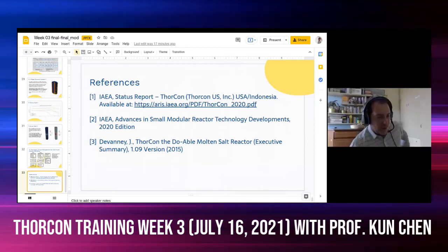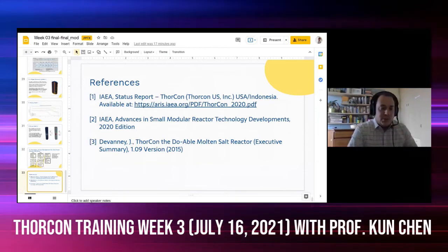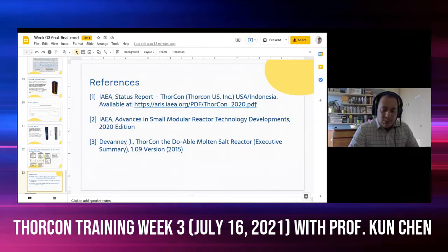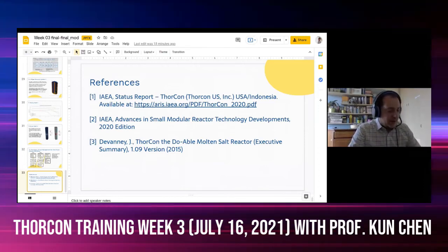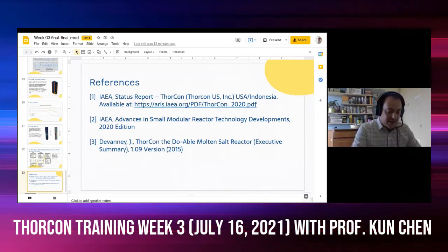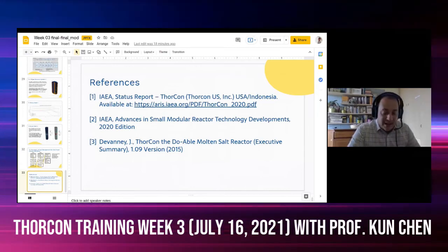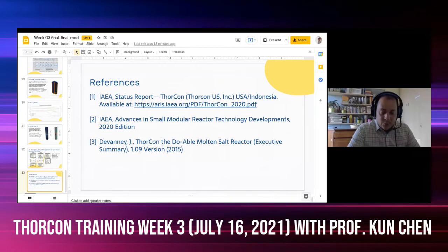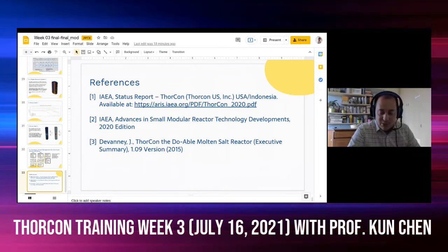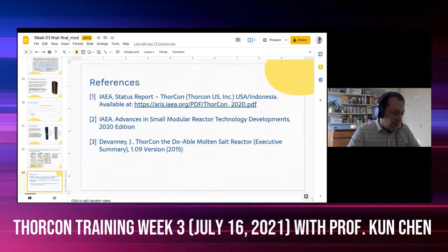Yeah, so there are 2 questions in this one. So I'll take the first one first. We use a specific set of tools based on Serpent coupled with OpenFOAM. Serpent is a Monte Carlo code developed at VTT Finland. It has specificity that makes it very suitable to do this kind of analysis, namely delta tracking, which implies that it can be coupled with finite volume codes very effectively. In our case it is the multiphysics code OpenFOAM.